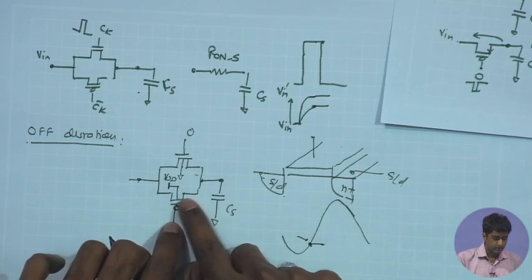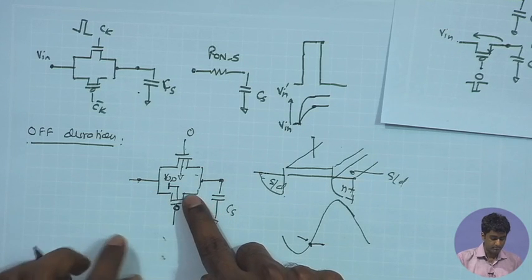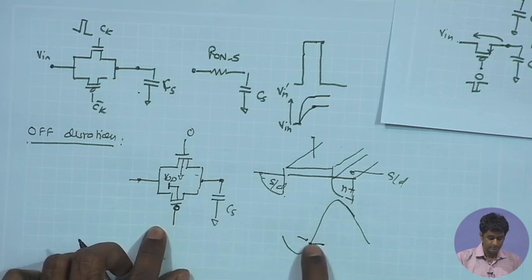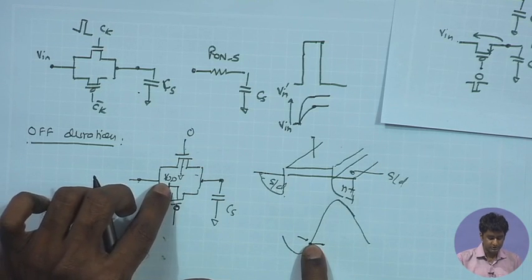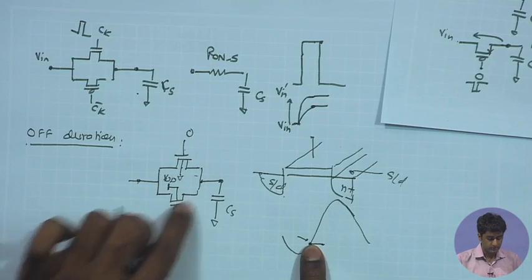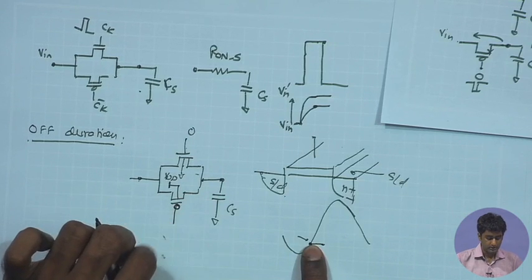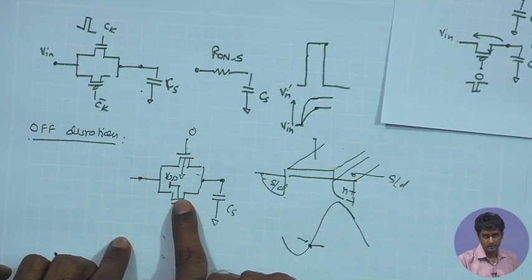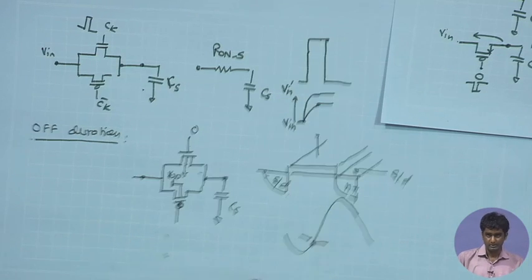Here we have for the PMOS a P plus junction over here which is relatively low, which is equal to the sampled value over here, whereas the substrate junction is VDD. Therefore, the reverse bias across the P plus N junction for the PMOS is going to be stronger in this case. What do we expect from there?